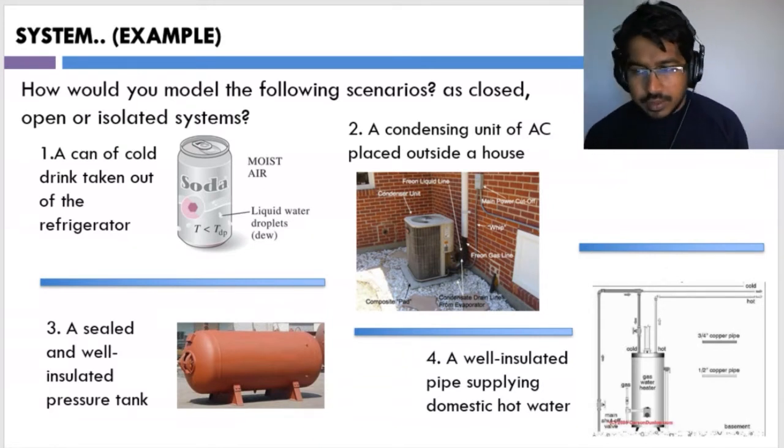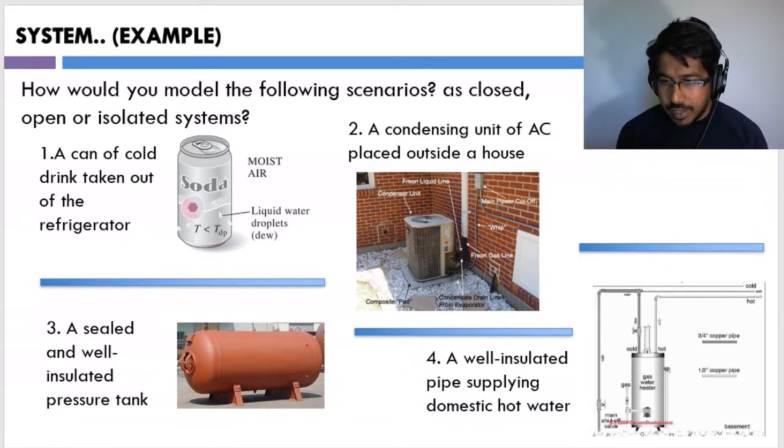Okay, we have two answers which are essentially the same thing, and I think you nailed it. The first one is a closed system, because if you think of a soda can that you take out of your refrigerator, you will feel the cold of the can, right? So it's not insulated, so the heat or thermal energy can cross the boundary, and at the same time if you do not open it, the mass cannot cross the boundary. So we can model it as a closed system.